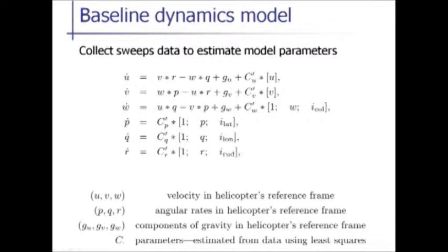We've got one control input for each of these axes that controls how fast the helicopter will rotate in each axis. Similarly, we've got a drag term and an offset to compensate for the fact that the controls aren't perfectly centered. We don't model any airflow or any of that. And we'll get into how this could possibly work soon.